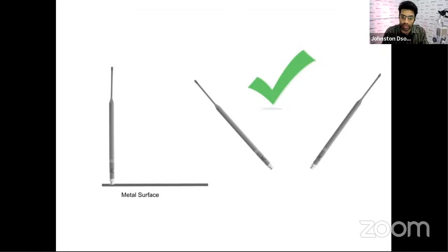If you're working in a corporate environment and you're using these small antennas like these that you then screen, then don't stack up your receivers, and mostly you'll be using wireless mics. So don't stack up your receivers there. You take a table and you kind of space them out, like 6 inches away from each other, so that the antennas do not affect each other. If it's a big problem and they're not giving you that much space, then I would suggest to go for a remotely settable antenna, or you get a distribution system where you can put a couple of antennas for multiple transmitters, receivers. Is that clear?